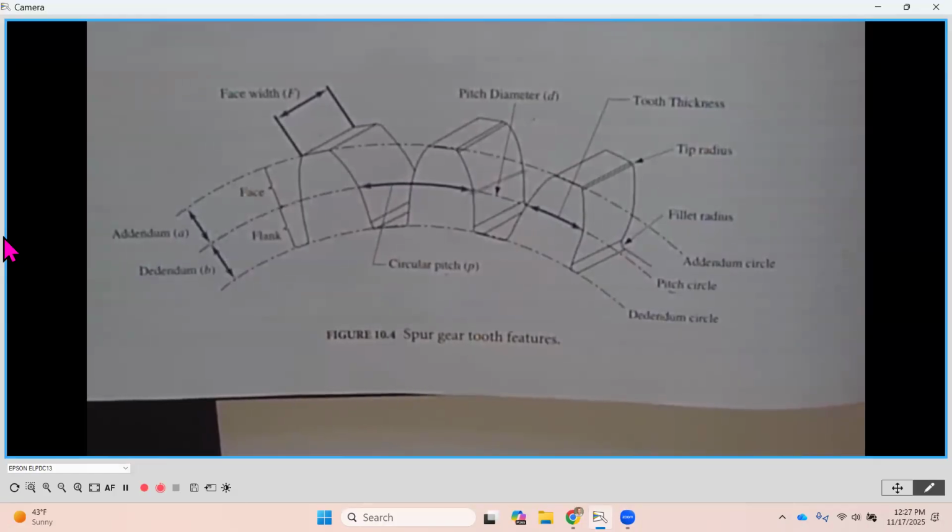In the next class, which I believe is spring 1, you're going to be taking machine design elements. And in that class, you're going to be kind of finishing up the gear design where you're going to determine what is the face width and what are the materials. And you're going to notice that when you're calculating stresses for the forces that are generated, the wider that face width, the lower the stress, because you're distributing that force over a longer distance.